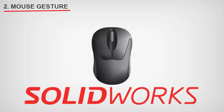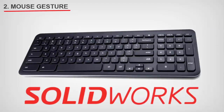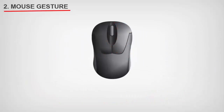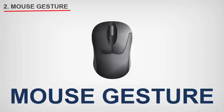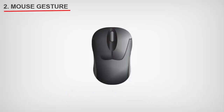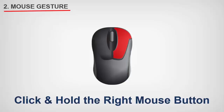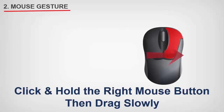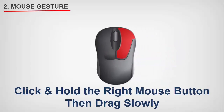In SolidWorks, not only the keyboard has shortcuts, the mouse has shortcuts too. The mouse shortcut is called mouse gesture. To use the mouse gesture, we can click and hold the right mouse button, then drag the pointer slowly in one direction until the mouse gesture appears.